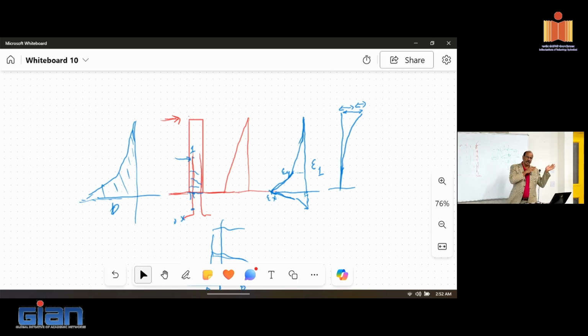So when that happens, you pull this out, it's rotating, that rotation times the height of the column. So now you go back to some of the connections I showed earlier, even if you have a coupler in a critical section at the face of the column connecting to the beam or column to column, if you develop strains or moments in the higher level, the same phenomenon will have to take place, right? I can actually approximate and do a very good estimate of what this displacement is, but I must account for the effect of the penetration.